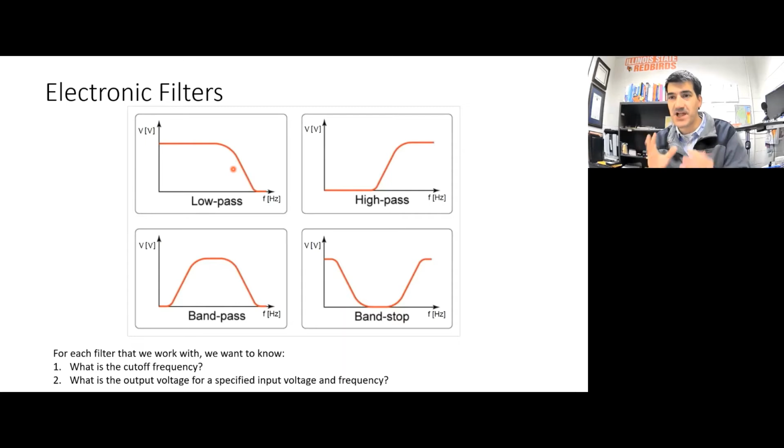It's not really blocking. Sometimes we'll say that, but that's a simplification. Because what we're going to talk about is something called a cutoff frequency. And for right now, you can just think about the cutoff frequency as being right around this knee right here. For a low pass filter like this one, generally it's going to pass the low frequency portion unattenuated, and it's going to attenuate the high frequency portion that is above that cutoff frequency, about right there.